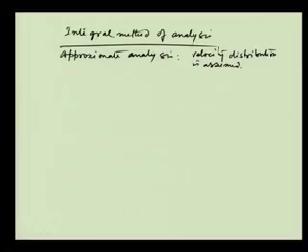In this integral method, we consider the momentum or energy balances for the total boundary layer, integrating from y equal to 0 to y equal to the boundary layer thickness. So, we do the integration and find out what is happening to the energy equations as well as the momentum equations.